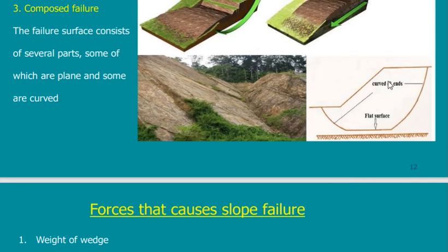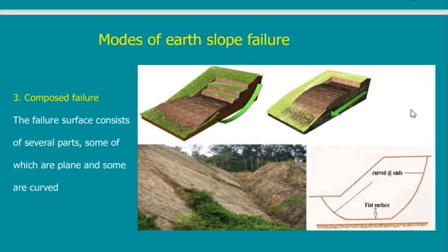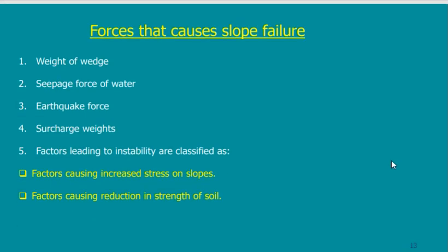Surcharge weight. If I come to this slope and imagine that you build a building on top of here, this building will help the slope to fall more. Why? Because you are adding weight to the own weight of the portion that is going to fall. So any surcharge in this area will add to the forces driving the slope to fall.